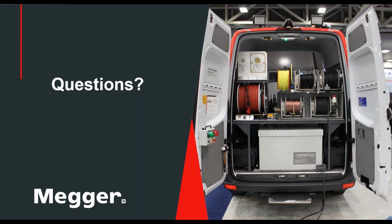So I can now flash over to that armor, and I have a ground again. So I can use some of the fault locating methods for medium voltage cable also on an armored low voltage cable. When I have an armored medium voltage cable or high voltage cable, and my fault is between the center conductor and the metallic shield, that armor doesn't have any influence on it.